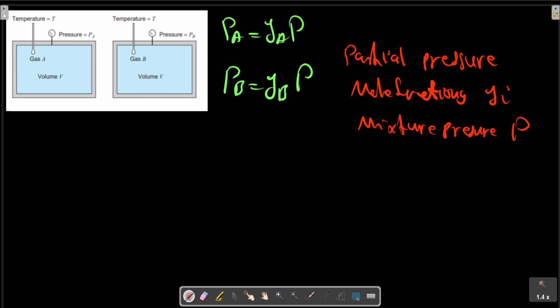In determining the internal energy, enthalpy and entropy of a mixture of ideal gases, the Dalton model proves useful because the assumption is made that each component behaves as though it occupies the entire volume by itself. Thus, the internal energy, enthalpy, and entropy can be evaluated as the sum of the respective properties of the constituent gases at the condition at which the component exists.